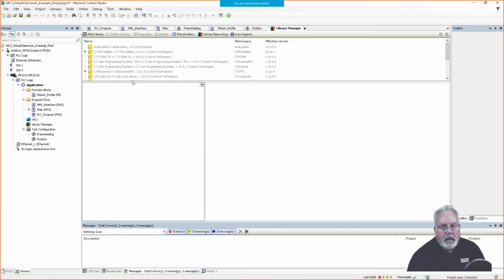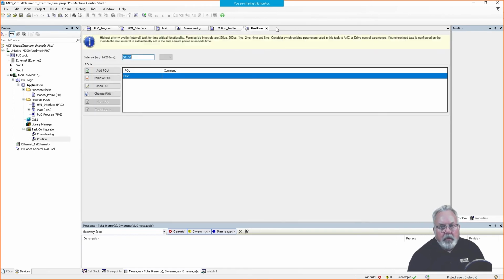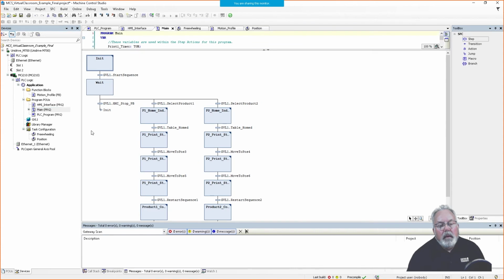Okay. Now, sequential function chart. Let's look at that. Here's what a sequential function chart looks like. Okay? The beauty of this, and you're going to see this tomorrow when I run it, is it is literally going to step through these steps. This is a transition. And what that means is I cannot get out of this until that's true.